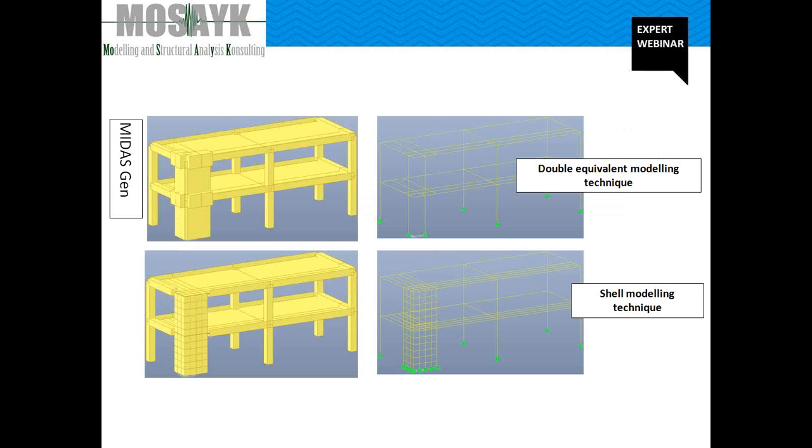If we move to a torsional building, a building with high torsional effect, we can apply both the same modeling as before, the beam equivalent model, representing with master node and slave node the geometry of the structure, and an L-shaped wall on a corner may also be modeled using a shell approach.